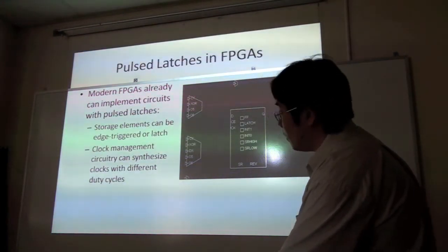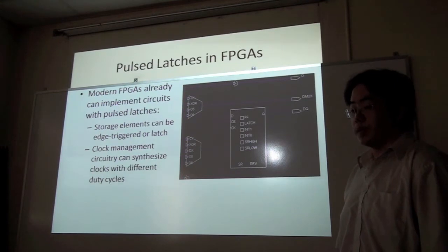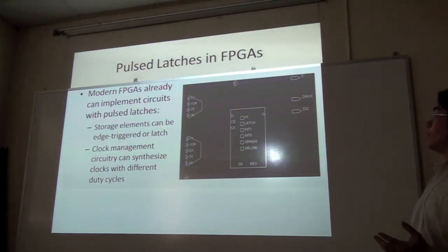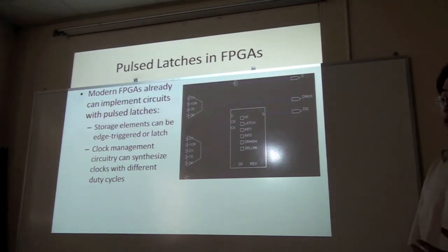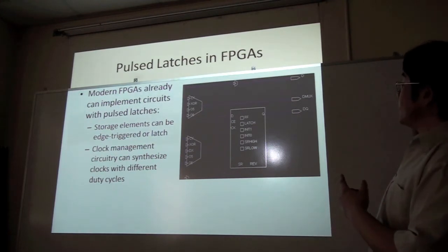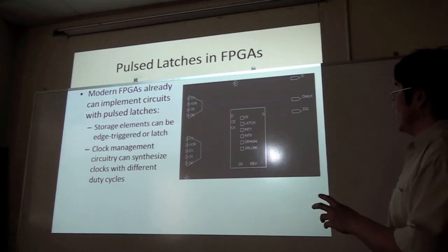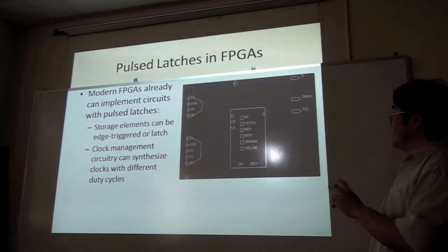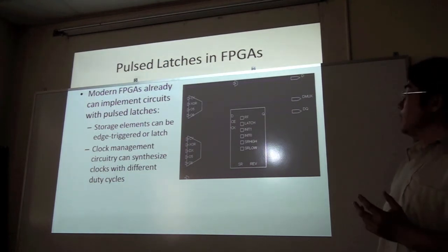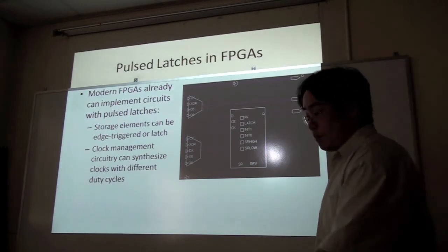Another reason for pulse latches is that modern FPGAs already have the functionality for us to configure an edge-triggered flip-flop to be a latch. On the right here is a screenshot of the Xilinx FPGA editor showing a sequential element that can be configured as a flip-flop or a latch. As well, there is already dedicated circuitry that allows us to synthesize clocks with different duty cycles.